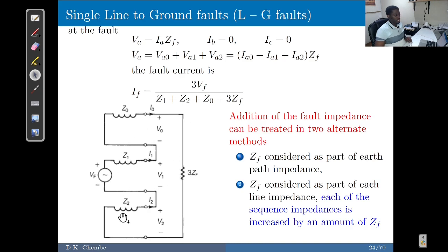So this is the connection that we mean, that first we have to determine the bus impedances for each sequence, which is the zero sequence, the positive sequence, the negative sequence, and then connect them depending on the network setup. So if it's line to ground, this is how they are going to be connected, in series.